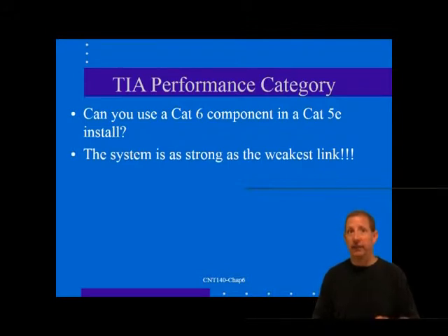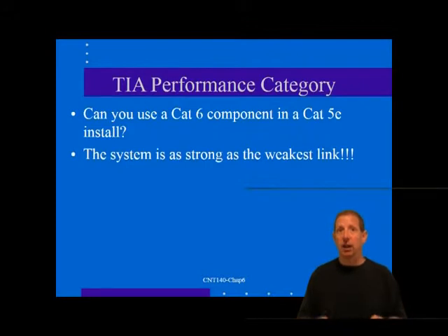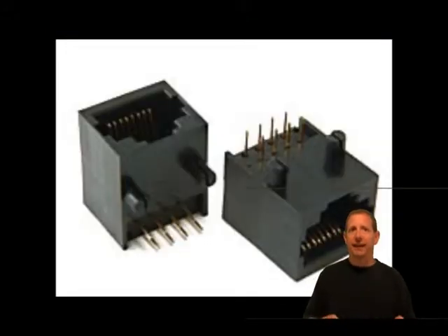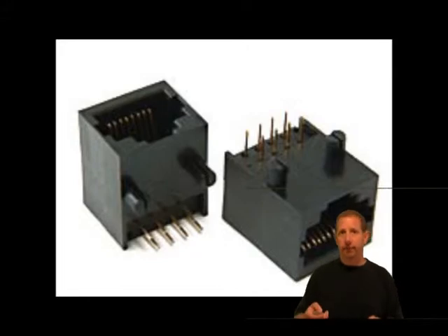The IDC jacks are so easy to use, they are often used even when their higher category of operation is not required. Now, some modular jacks have an extra slot on the side to supposedly limit connections to cable plugs with a matching slot. These side key jacks are largely useless because they easily accommodate a non-keyed plug.